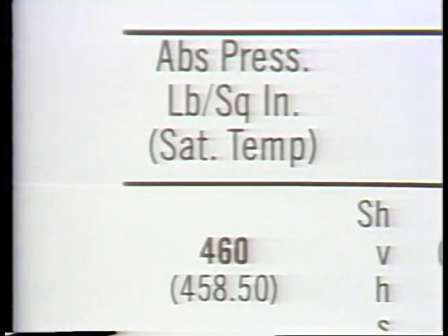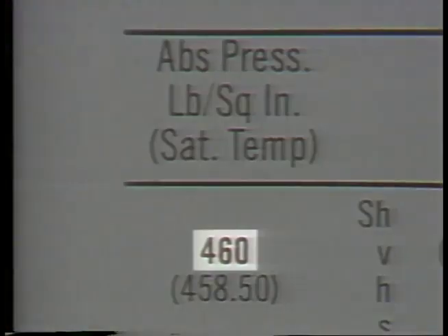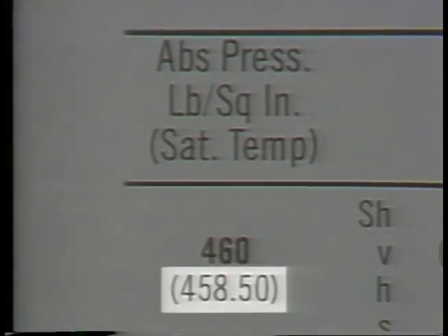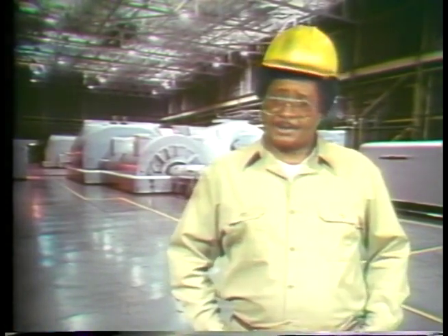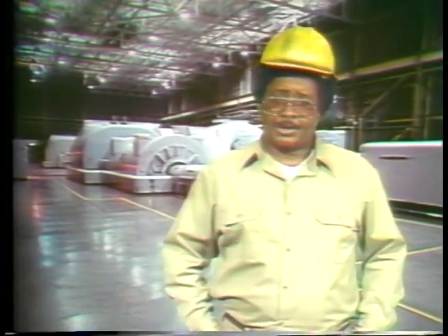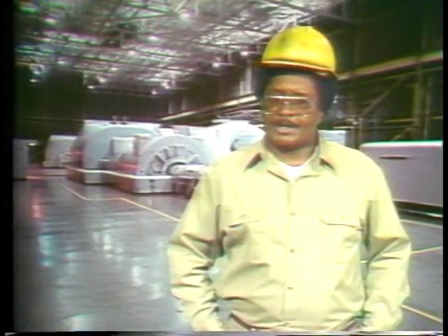We look through Table 3 until we find the desired pressure, 460 psia. Directly under the pressure value is the saturation temperature for 460 psia. It's 458.5 degrees Fahrenheit. Since our outlet temperature is 680 degrees Fahrenheit, and this is higher than the saturation temperature, we know the process is superheated.